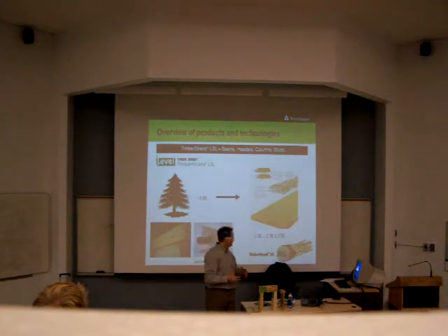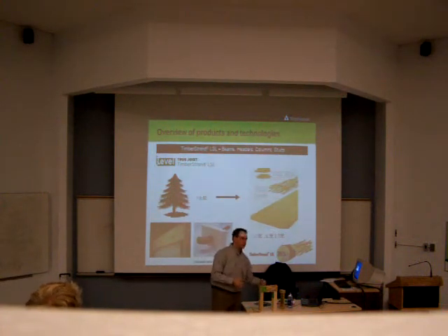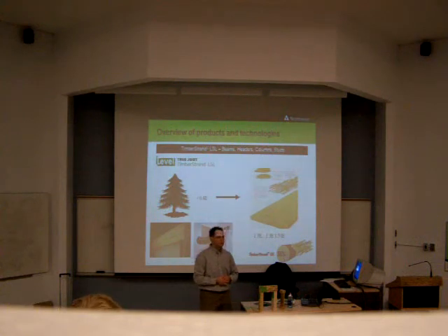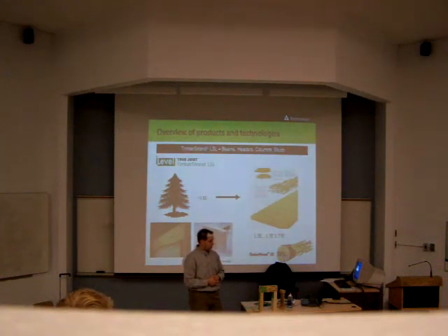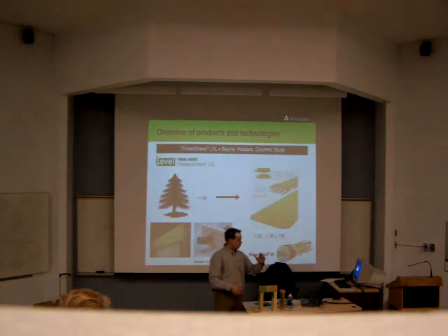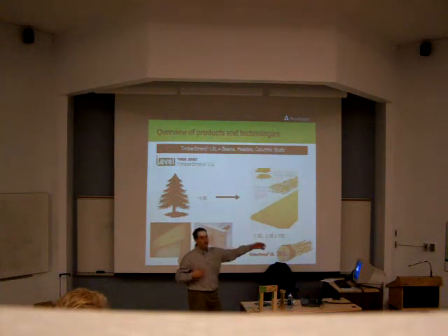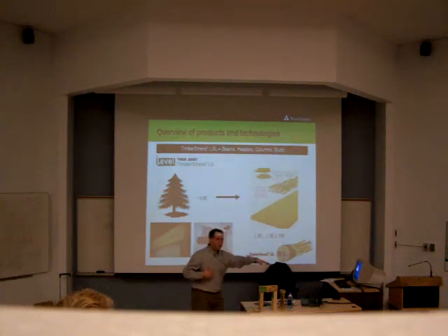And also, because of its composition, it's very, very dense, still workable. You can cut it with a saw, you can nail into it and all that stuff. But it's a lot denser than a piece of SPF, a piece of regular 2x4, which makes it very strong in crushing. So the role that timber strand has to play would be more for really shorter spans where bending isn't governing. The longer the span, typically the bending becomes more critical.